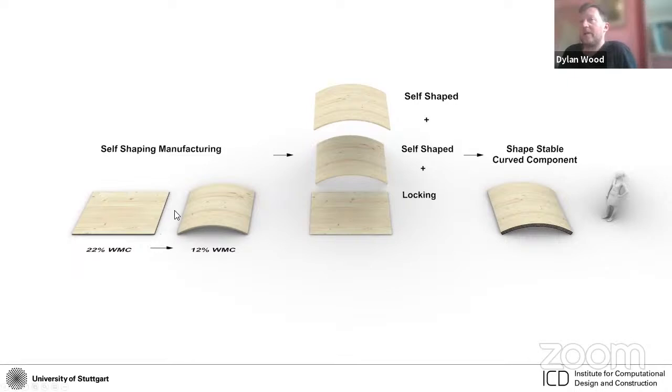So we can actually produce these 2-layer sheets, on the scale of multiple meters, in a flat configuration with design thicknesses and a couple of other parameters. When these pieces are dried, they will form curved sheets. Then we can combine these curved sheets again in order to lock the movement in place, to get a highly curved, form-stable CLT component with which we can build.